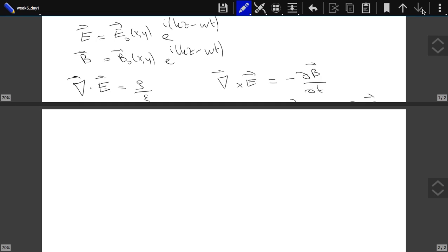And now these Maxwell's equations I will write inside my waveguide. Well, inside my waveguide I cannot have any current, I cannot have any charge, it's empty. I started with assuming the waveguide is empty. On the conductor, I can, of course, have currents and charge density, but not inside. So, divergence of E is equal to 0.